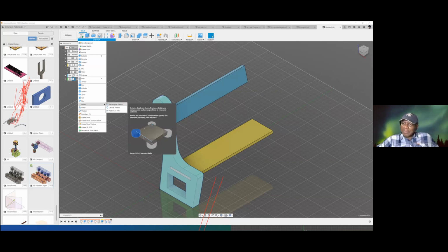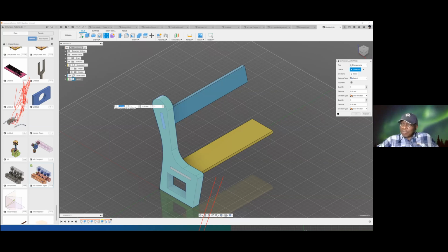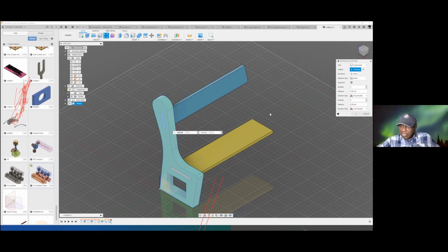And then, what type? It gives you this drop down. The type is component. The type could have been faces, bodies, features, components. But it's component. An object is already chosen. Select this object. And there is a direction for it. If you turn on your origin, the direction we want is the direction of the y-axis. So it knows it is going to create it on this side.